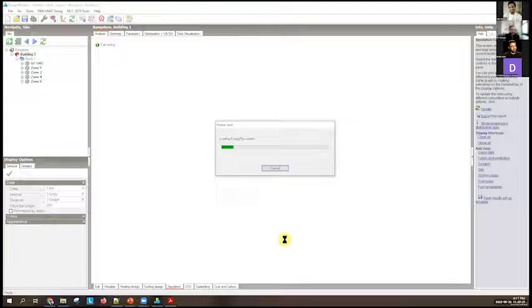If I didn't want to use DesignBuilder as the interface for the output, then I needn't wait for it to load the results. And what you'll find is that in many cases, the energy simulation time itself might be quite small, but loading the data back into the DesignBuilder interface is quite time consuming, like you are seeing here.